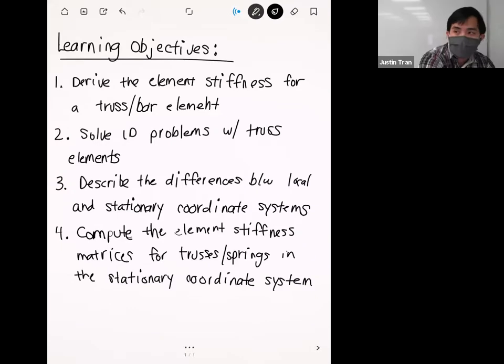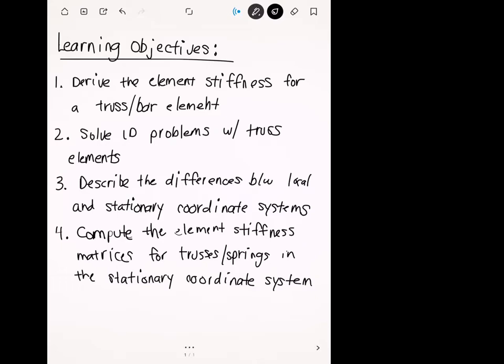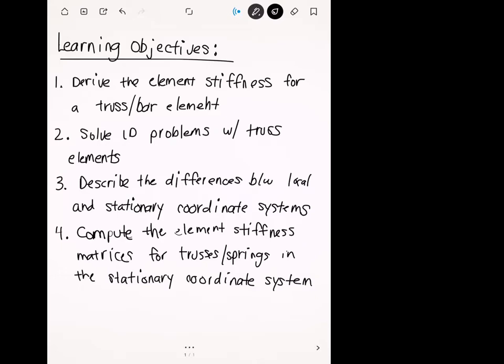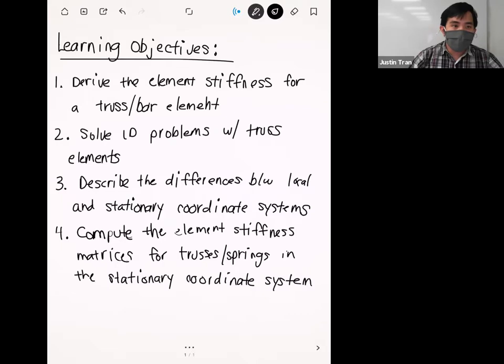Professor, question for you. Yep, sure. What's up? For the answers, I've been trying to make a moment in it, and so far I haven't been able to create a moment about the X or the Z. It only allows me to create one about the Y, depending on the orientation of the object. Is there a way for me to do a moment about the Z and the X? Yeah. Just like we do for forces and pressures, you can change the defined by, I think it's vector, to components. Then you can individually set the moments in whatever direction that you want.